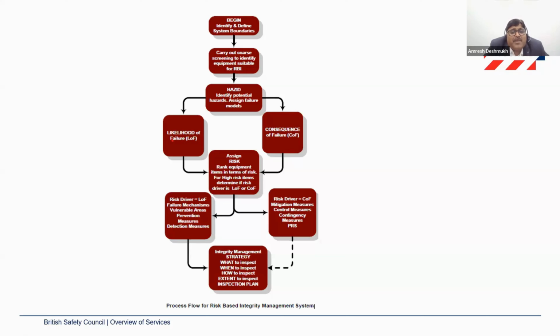And if I'm having a good hold on the various degradation modes or the failures, I would have information well within time before the primary containment fails to ensure that I devise the preventive maintenance program for a particular equipment, or I modify my inspection plan in such a way that this primary containment doesn't fail, or I would ensure that it's actually tested well within time before the failure happens, and that way I'm strengthening the preventive mechanism for my asset integrity program, and at the same time I'm further improving my asset integrity strategy also.